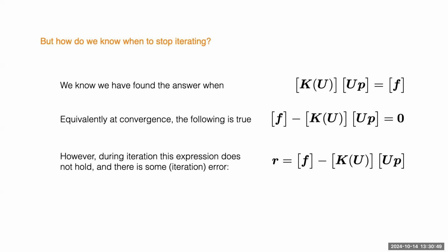So if this equation represents a conservation of linear momentum, like a force balance, then this residual can be thought of like a force imbalance for every cell. So that's another way to think of it. Or if it's representing conservation of mass, it might be a mass imbalance per cell.